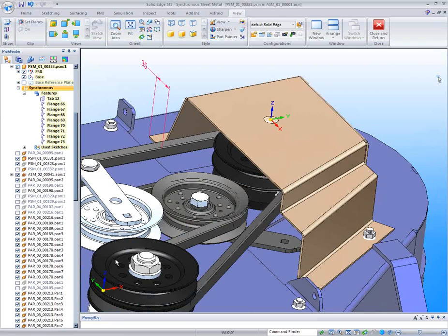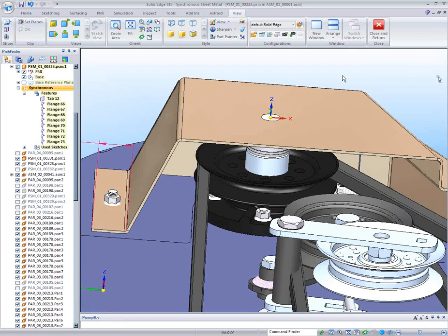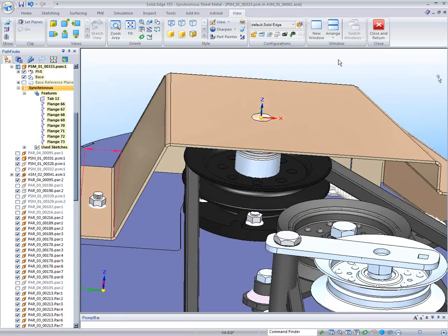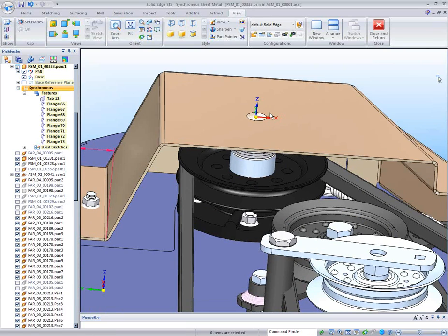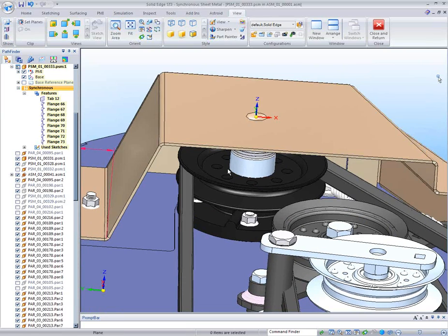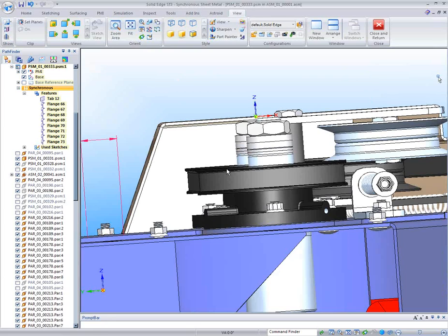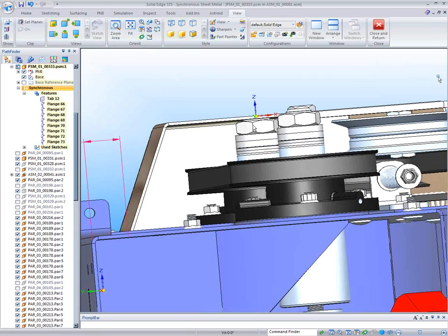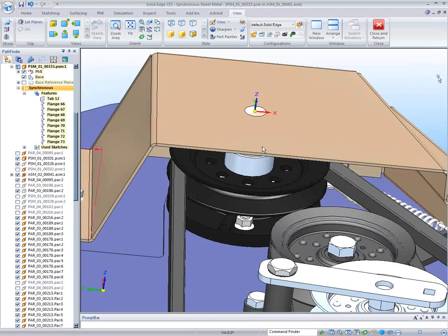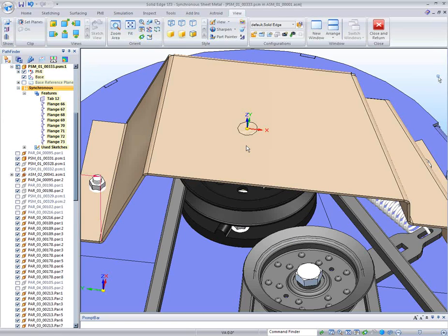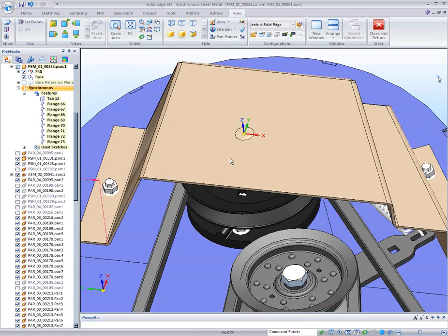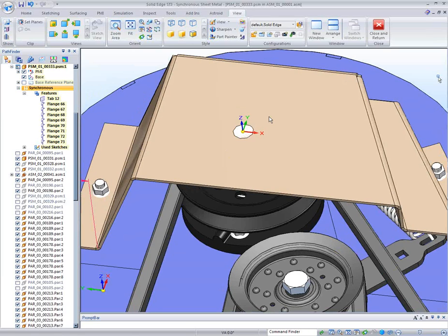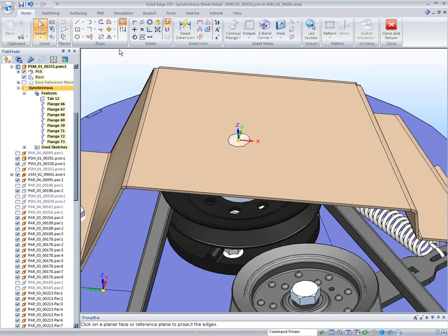But speaking of fitting, I want you to see this bolt, this shaft right here. Spin around down here. Once you see the shaft right here, the top of that nut is actually interfering with that plate. So I'd like to put a little bit of a relief up there, and for that I'll go back over and use my project to sketch.